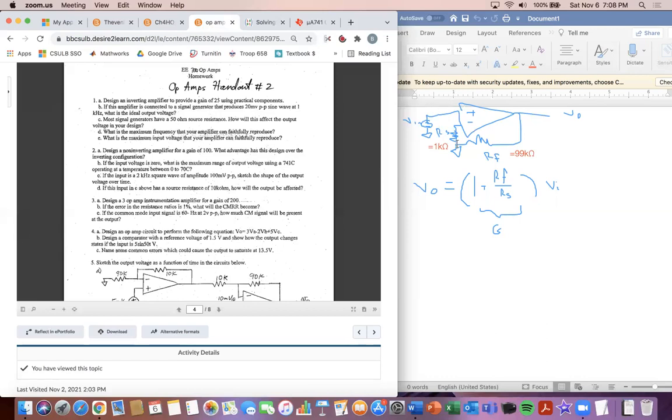However, if the voltage source is hooked here to the negative terminal, it would be in series with RS and be causing that to mess up the gain here, and that would not be good because it would be multiplying the transducer's noise. So the reason we have it on the positive terminal is because there's infinite resistance here, and it won't affect the value of RS in this equation. And so that's why we use the non-inverting amp. So here I'm going to say in phase with output because there's no negative sign, and also good for transducers.